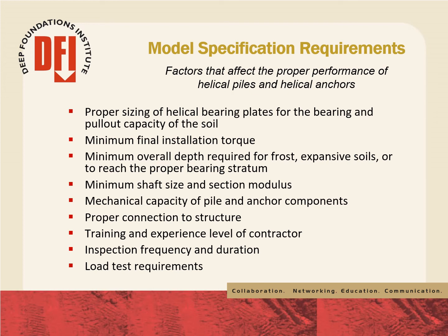The following list are factors that affect the installability, load capacity, and performance of helical piles. Several of the most important are proper sizing of helical bearing plates for the bearing and pull-out capacity of the soil, minimum final installation torque, and mechanical capacity of pile and anchor components.